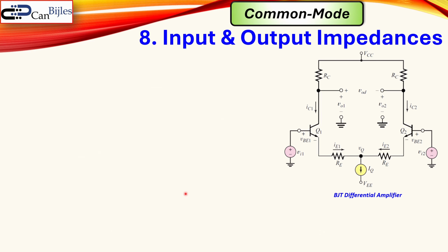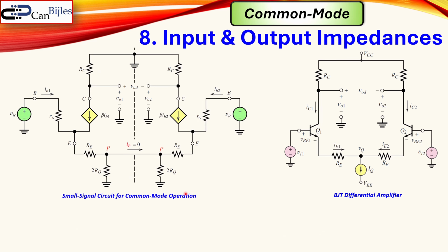Now let's look at also the common mode circuit. Again, our small signal circuit then for the common mode operation. Let's also look at the input impedance first. How about that? Well, now we do not have anymore here a virtual ground, but we have the same voltage here and the same voltage there. That means our half circuit is actually now in parallel. And since we have the same impedance from this node to ground, we actually have then the impedance from here to ground divided by 2. That's actually what I see here.